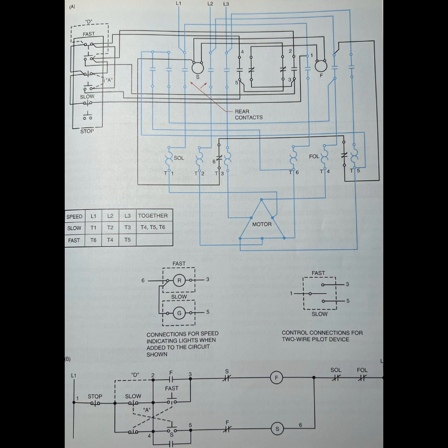If equipment considerations make it desirable to stop the motor before changing speeds, this feature can be added to the control circuit by making connections E and A by the dashed lines. Adding these jumper wires eliminates push button interlocking in favor of stopping the motor between speed changes. This feature may be desirable for some applications.